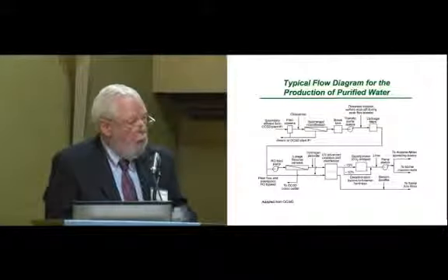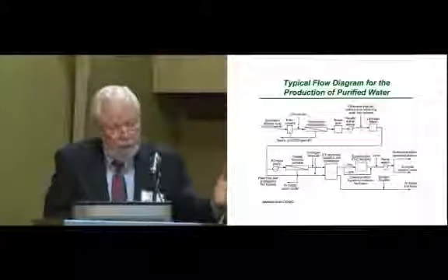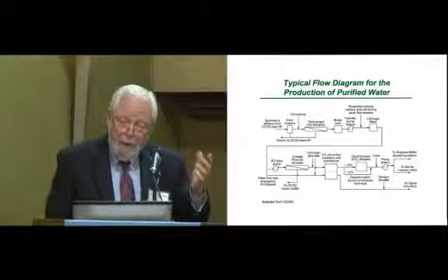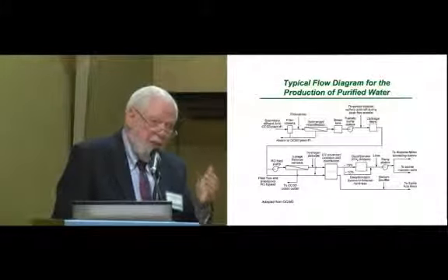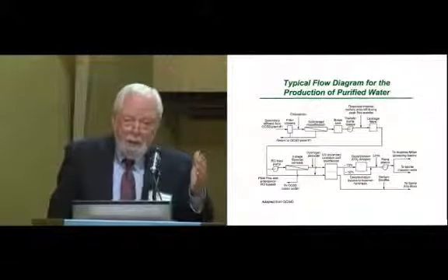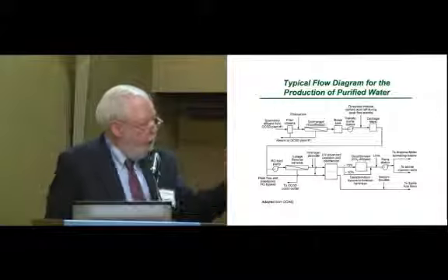It's interesting. People say, well, why cartridge filters if you have submerged microfiltration? And the reason for that, of course, is that the chemicals used to prevent scale are not highly purified. And so to remove the impurities from those chemicals, you need cartridge filtration.